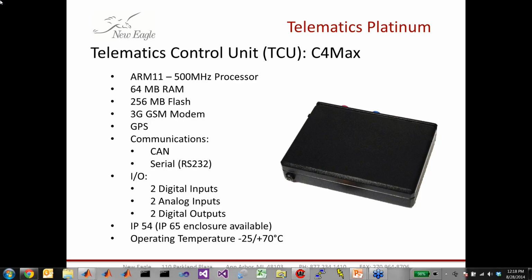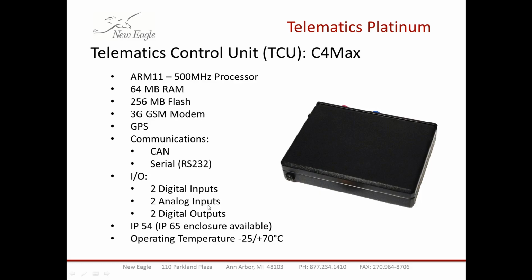Question comes up, how many CAN buses can this handle? It has only one CAN bus. One of our existing projects, though, has another module act as a gateway when there is data that needs to be logged on multiple buses, and that has worked quite well. So that question probably stems from my earlier comment about the amount of data that can take place on a CAN bus or multiple CAN buses.